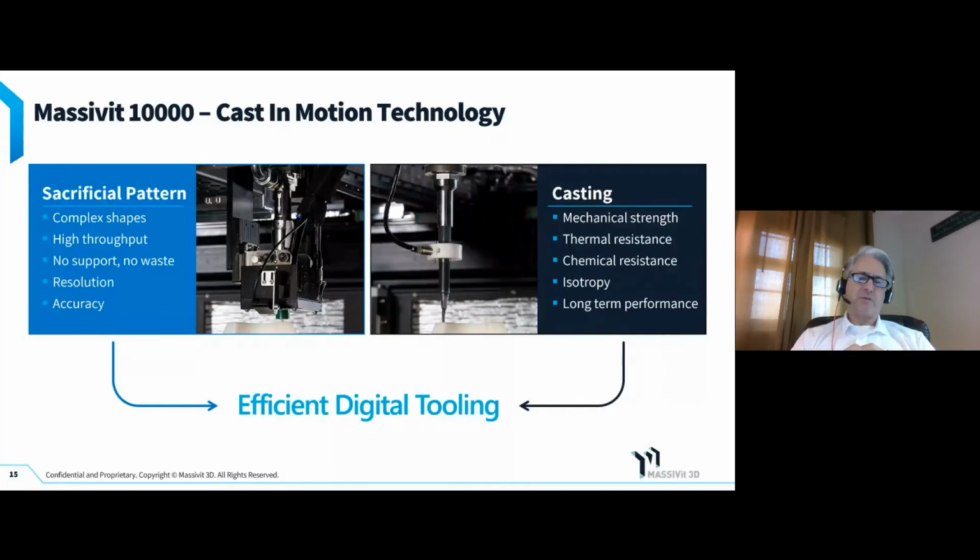we're doing two things. One, we're controlling the exotherm. The open time on the epoxy when it's mixed is about 20 minutes. And the other thing we're accomplishing is all those pour intervals are blending together because of the open time. And as they blend together, they create an isotropic, rock solid mold. So you don't have any delam issues, you don't have any air pocket issues, and in the X, Y, and Z, you have the same coefficient of thermal expansion.